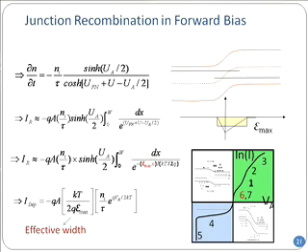If you divide with E max, which is the electric field, what do you get? You get a dimension of a space or distance. So that is sort of the effective distance over which recombination is occurring. The right-hand side, do you agree that that's essentially the extra carrier concentration that you have in the junction region, exponential of QVA over KT.